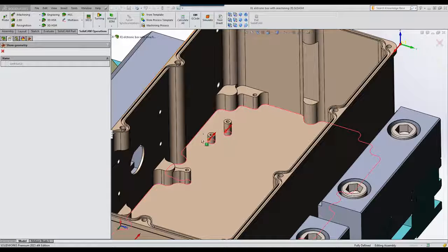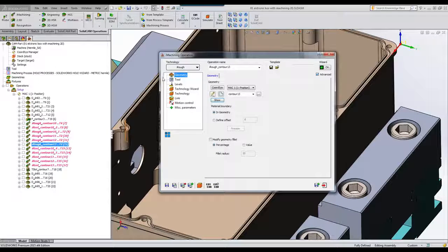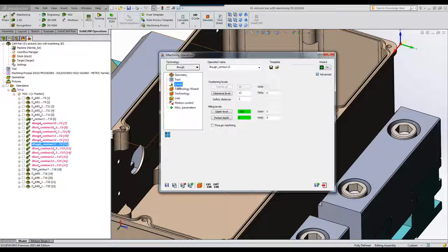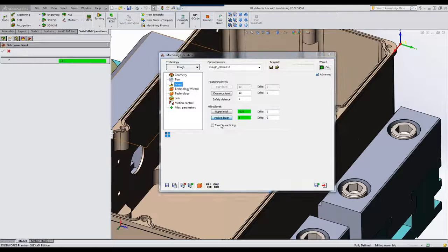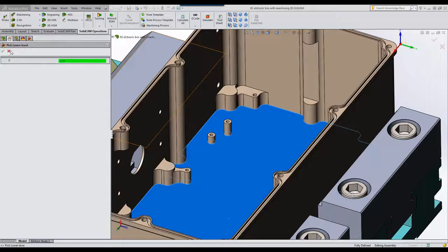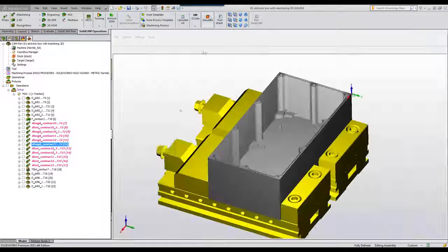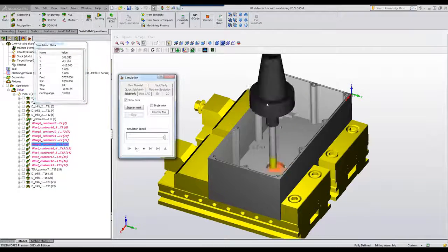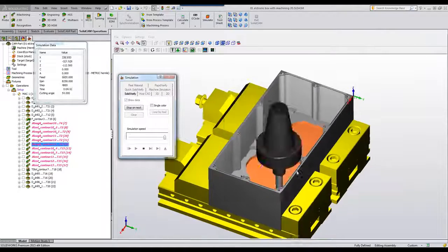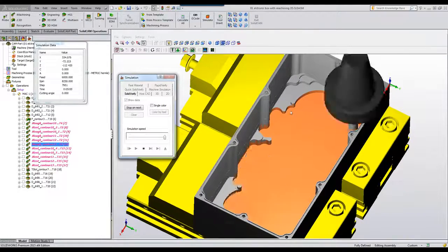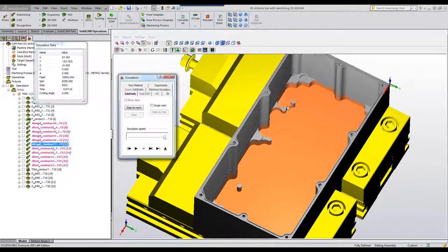And now it's going to go down from this height over here up until the floor. Okay, the same tool, levels, a total of 8 millimeters, going down to the floor itself. Running my simulation. You can see now this one finishes off the floor. And you can see our two little studs at the very bottom over there.